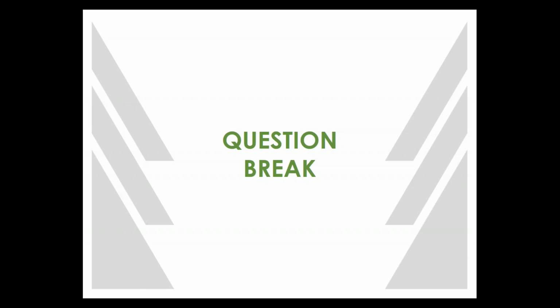Okay, thank you, Scott. All right, we do have another question that came through our chat box, on the section on in-unit HRVs and ERVs. The question was, for through-wall HRVs, would additional measures need to be taken to ensure proper air distribution for the other rooms within the unit? Yeah, so that was that photo of the through-the-wall ERVs or the packaged ERVs. And yes, once again, those are decisions that need to be made thoughtfully for the space that it's supplying.